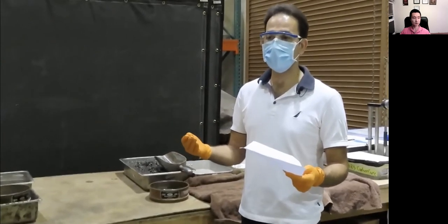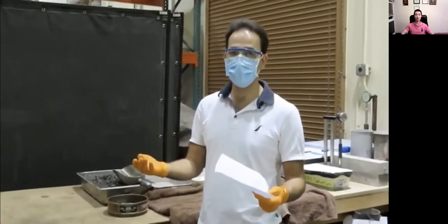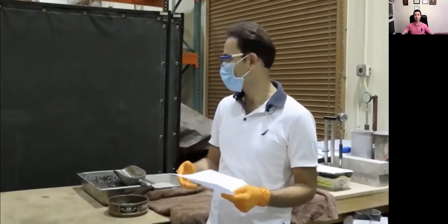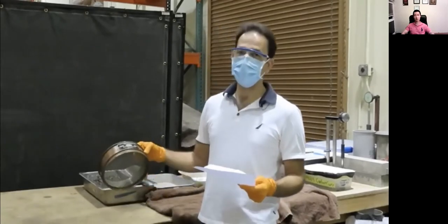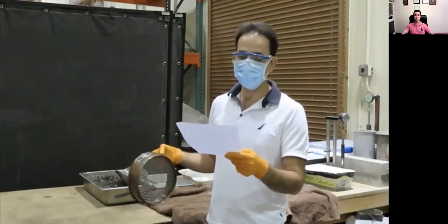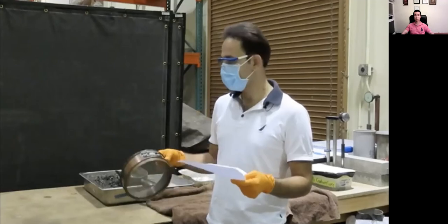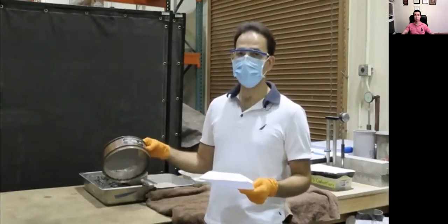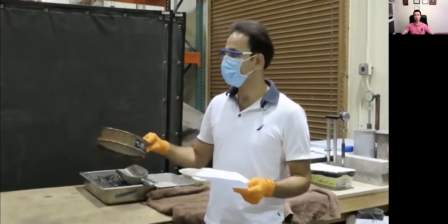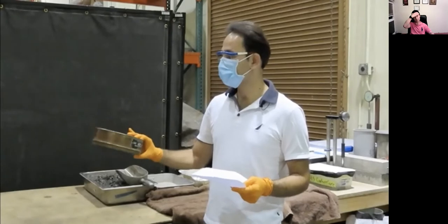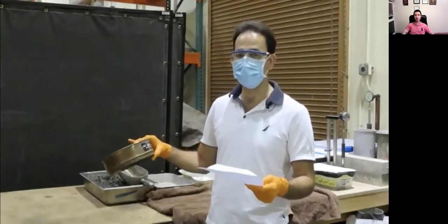It means that I need to fill all the voids inside the aggregate with water, so it needs 24 hours to penetrate into the aggregate. For part 1, I need to use sieve number 4 according to the experiment number 8 in your textbook on page 564. I need the sieve number 4 because it's a borderline between coarse aggregate and fine aggregate, and also it helped me to get rid of the excessive water, so I can dry the surface easier.